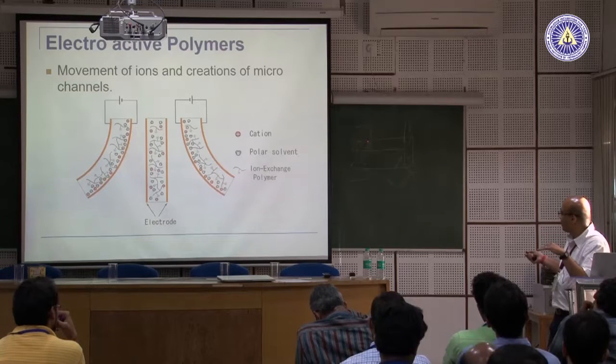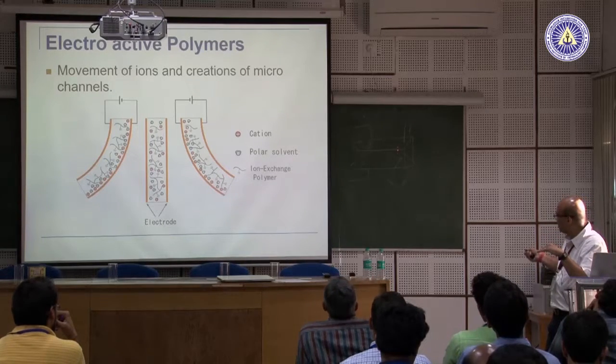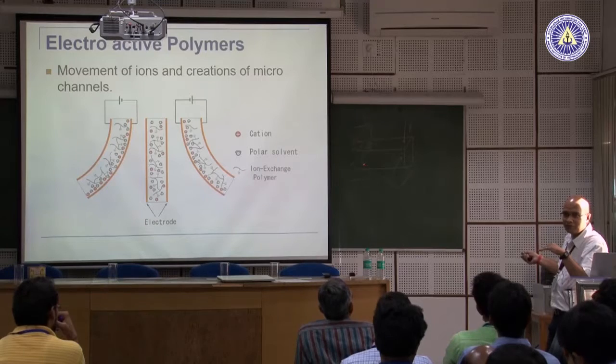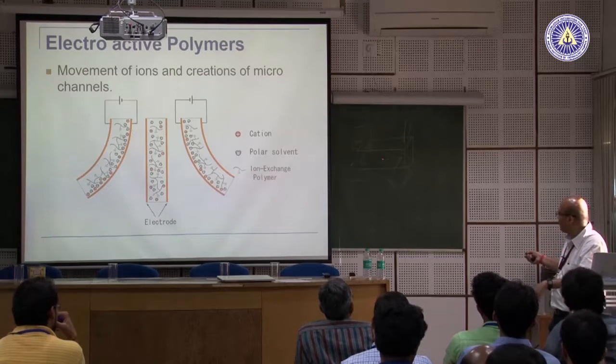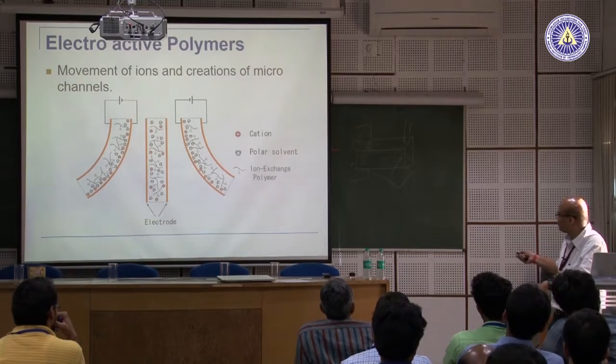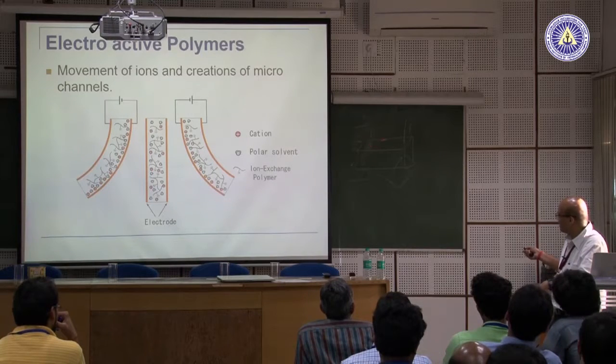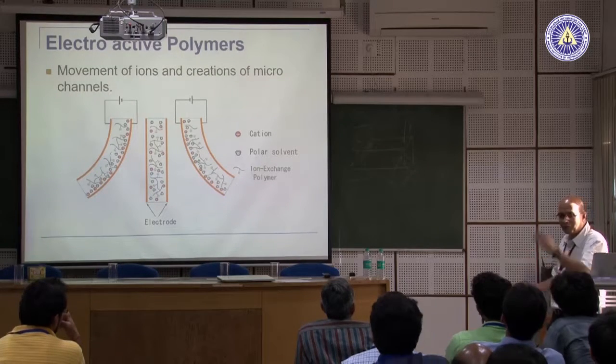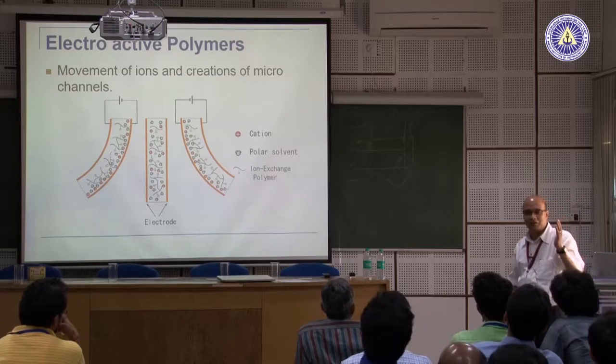But now, if I put an ionic polymer and suppose it is vibrating downward or it is trying to move upward, and I actuate it such that it tends to move downward, if you understand what I am trying to say. I put an ionic polymer strip here, I take this actuator, put it here. It is going to sense that this fellow is vibrating, but I actuate it such that when this fellow is going upward, this fellow will tend to push it downward, and if this fellow is moving downward, it will tend to pull it upward. So, it will cancel your vibration also.